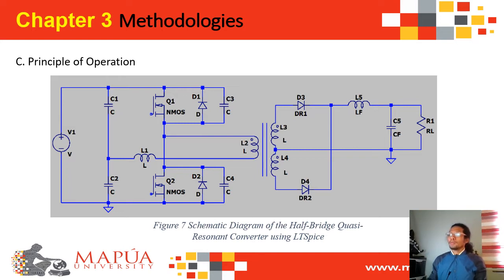At the end of the conduction period of transistor Q1, the voltage across C1 is 0, whereas the voltage across C2 is equal to the supply voltage, and the output current flows through the R1, and the primary current is I0 over N, where N is the transformer ratio. Vice versa for the C2, where the process is the same as the preceding explanation.